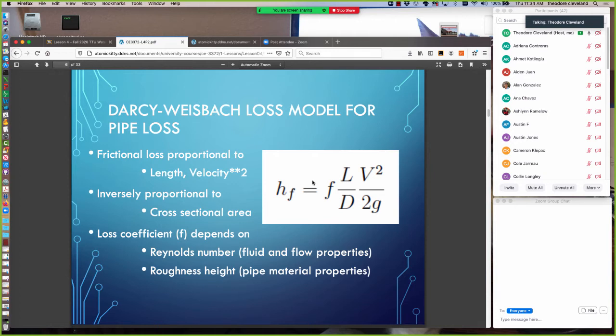We also see that as our pipelines get longer and longer, the head loss increases. Since the purpose of them is to move water from point A to point B, we don't have a whole lot of degrees of freedom on the overall length. If we can cut diagonals instead of having to follow street grids, there's some advantage to that, but it's not a whole lot.